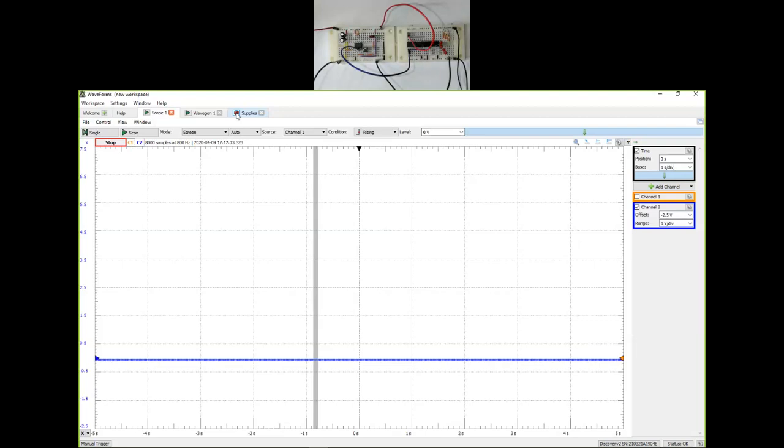However, the problem is this: because we have increased the capacitor a lot, we have essentially assumed that we are not going to press the button between 100 millisecond and 200 millisecond. So we cannot press this increment counter too fast. That is the problem of getting that hardware debouncer to be very good. So that's a trade-off that you have to make in the design.